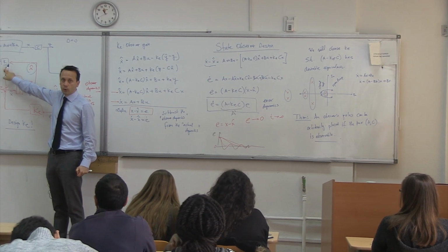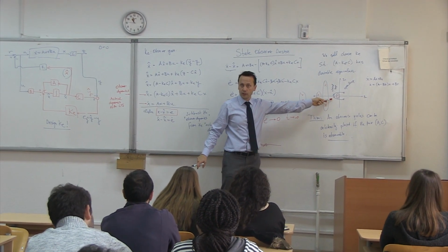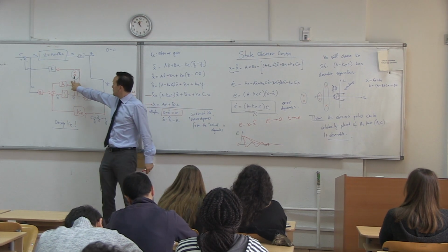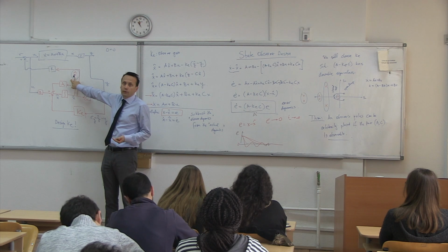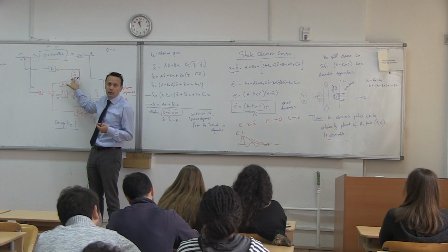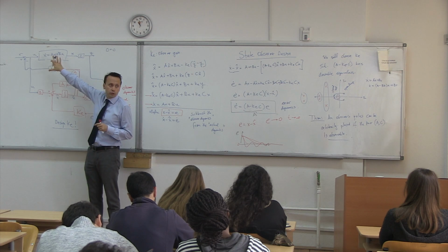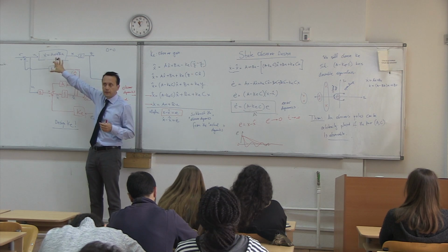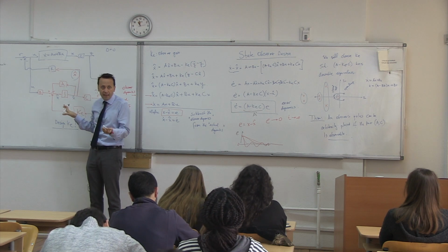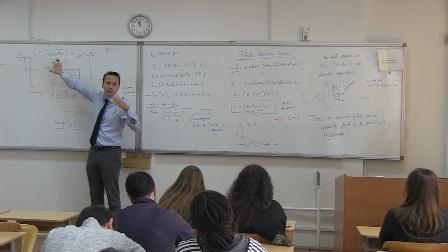And I'm expecting the closed loop to converge faster than this. But it can't because it's feeding the wrong x hats. So how can this part converge with wrong x hats? I need the correct x hats first and then expect this to converge. Do you understand that part? So therefore, the convergence of the observer must be faster than the closed loop if you want the closed loop to converge in a certain time.